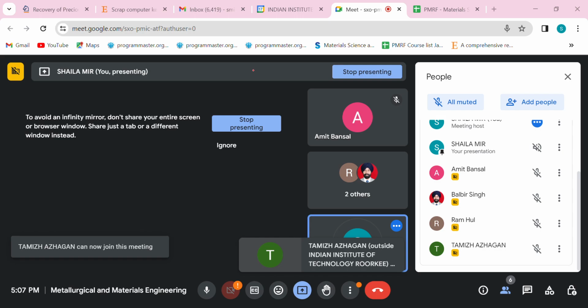So basically, when you are putting a dye inside a material, and then you are putting a developer on it, the developer should have the property that it should pull out your dye material out of the defect or crack, and then make the surface visible. So by change of color, you can see it visually.